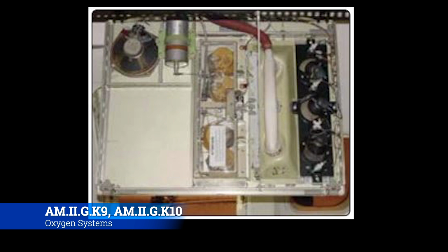Now, I'll tell you, a mask drop test is something that you have to do, especially on a 777, and it's not a fun night, because you'll drop all those masks to make sure that they all come down correctly, fix any problems they have, but then you have to repack all those masks. They have to be repacked in a very specific way, and they have to go up into those PSUs, and then the PSUs have to close.